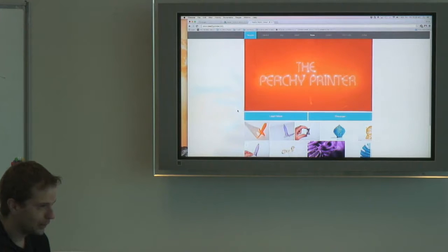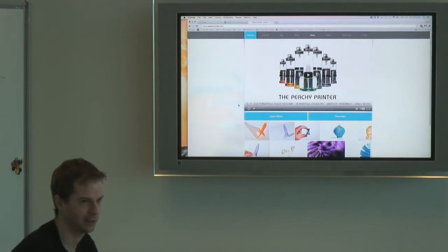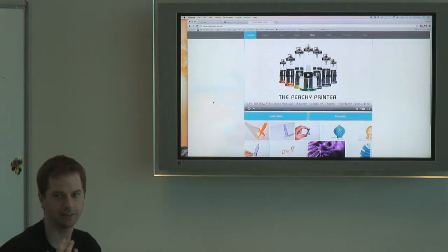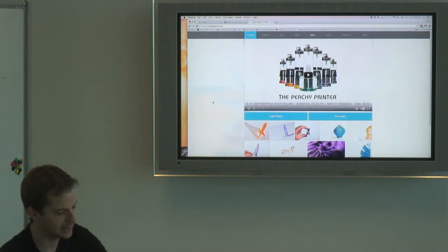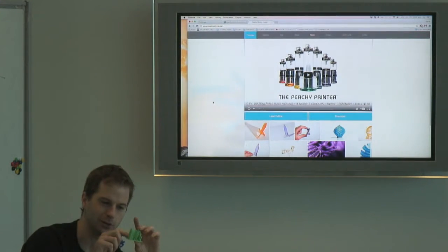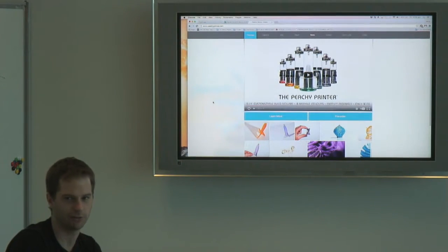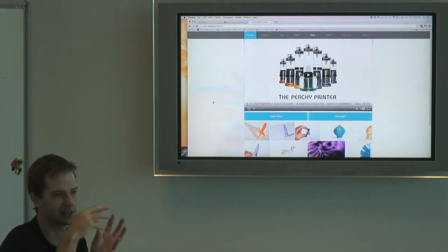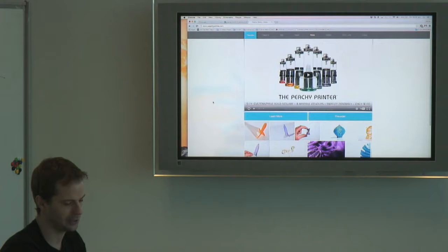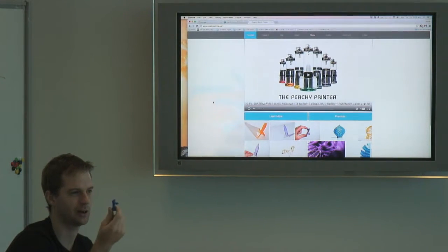Yeah, so pretty cool. And one of the cool things about stereolithography over fused deposition modeling is because it sits in its own medium, you can do hollow structures and stuff like that. Looking at these examples, you see that all the scaffolding which needs to be printed, because this is just floating, or on this one it floats in suspension, there's no scaffolding needed. As it prints, it just solidifies to the nearest part. So you could theoretically, rather than printing this and then spending all the time removing it, just print something straight out like that.